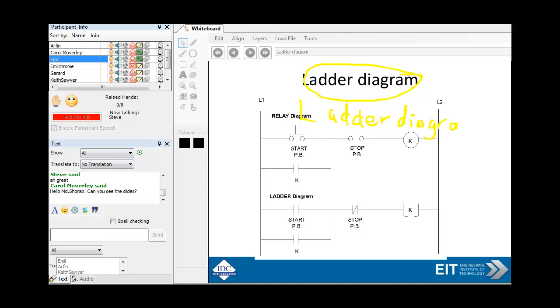Okay. Now, in this ladder diagram, all we want to show you is that there's a very simple way of writing a program. This is one of the most important programs, which is a building block of all PLCs. You'll always see this. It's always a test question as well when we set test exams. So the idea here is that you've got a start push button, and all we want to show is that it's a sealed contact.